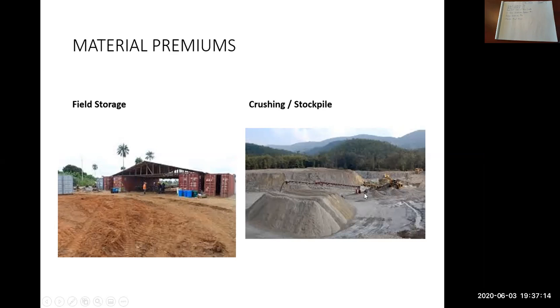Are you simply screening, or are you crushing larger rock into smaller rock to get fractured rock? Some types of gravel require crushed rock, like a road base needs to be crushed. You can't have round rock as a road base. So producing gravel, it's a specialty. Not anybody can do it.